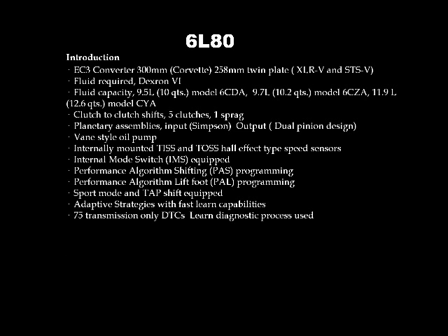The converters, we've got several different converters depending on application. So again, one size does not fit all on the converter application itself. Your converter will be matched to the particular vehicle itself. So not only is the stall-torque ratio matched, but also the K-factor of the converter is matched, obviously, to that vehicle. Fluid is required for this application.